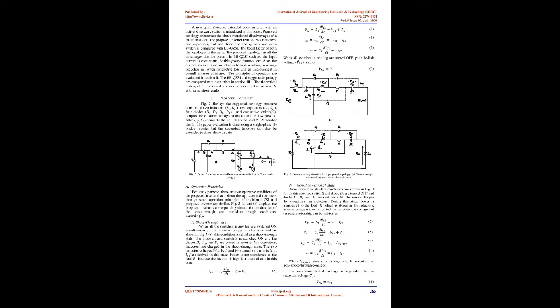To improve boost inversion ability, high voltage gain switched Z-Source inverter, HVGS-CSI, in [7] is invented. This topology brings together SBI and QZSI. But the problem with sharing common ground persists. By using cascaded networks, voltage gain can be improved. Extended boost ZSIs in [8] have 4 families. With the addition of LC pairs and diodes to the QZSI, other families can be realized to improve boostability. Besides, voltage stress across the capacitors is reduced in comparison to the conventional ZSI.